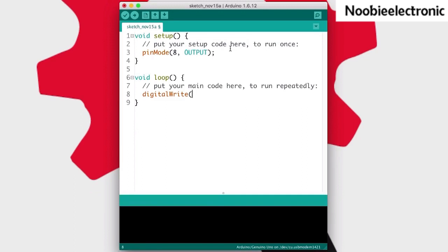So in our case, we want to take pin number 8 and turn it on. And the keyword for that is HIGH. So you can have a pin either at a high state or a low state, one or the other. There's nothing in between since it's a binary system. So I'm taking pin number 8 to the high state, which means that I'm going to write a 5-volt value to it. And I would like to keep that value there for a small amount of time.